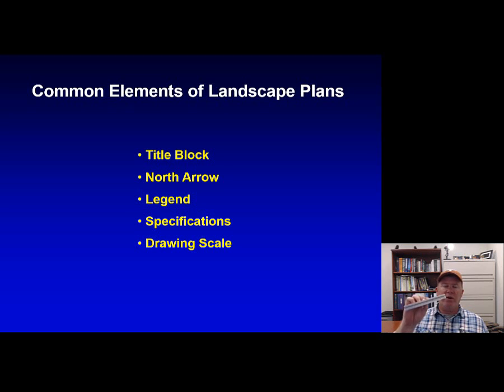When I say quarter scale, 1/4 of an inch on paper is equivalent to 1 foot on site. So you can see that the 1/4 inch is going to be a fairly large drawing, and that's probably the largest you would ever draw in.